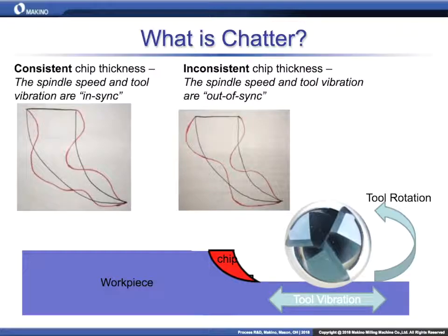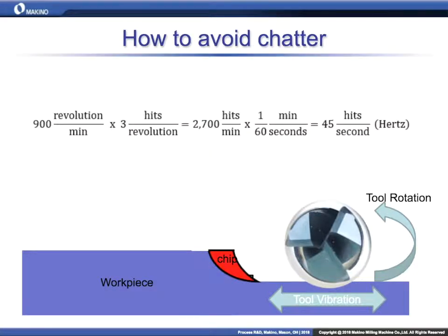Okay. So if we want to match that RPM, I'll let you walk us through that process. Now, how do we think about that in terms of these frequencies that we're dealing with? Right. So one half of that equation is we need to know what frequencies the tool vibrates at. We're going to talk about that later. Yeah. Let's figure out how to relate our spindle RPM to what we're going to call the tooth passing frequency.